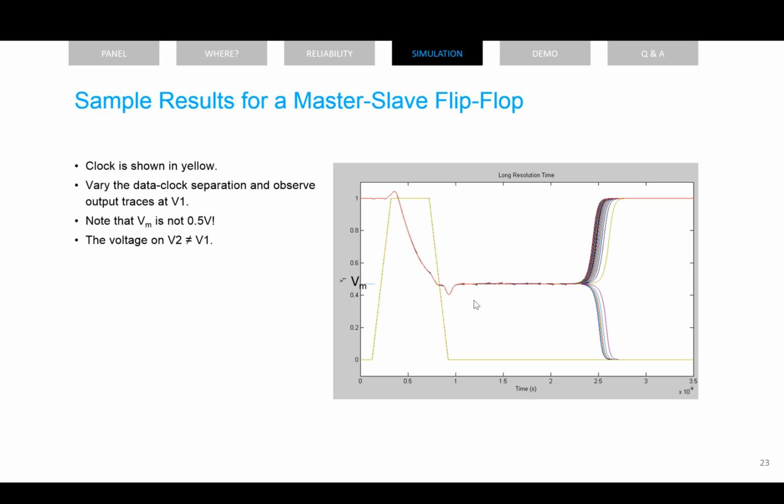The only way to really see what happens when the latch exits metastability is to adjust the D to clock timing to force Q to go metastable. The result of doing this is shown here. It's tricky to make SPICE do this. An arbitrarily long metastable time is shown, but it can be done.